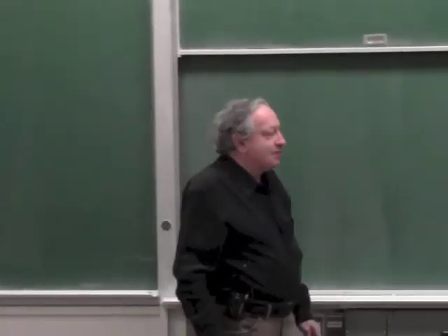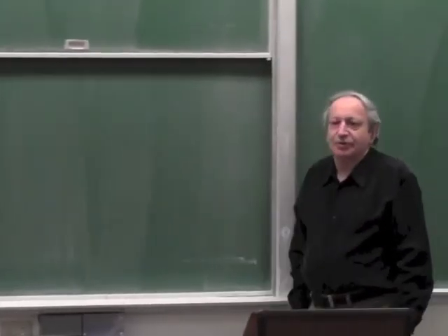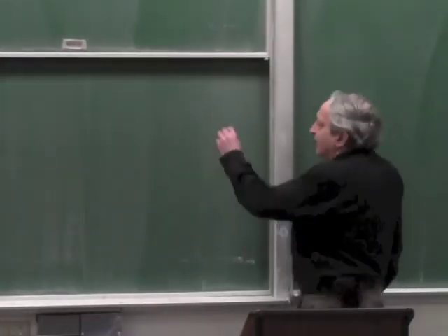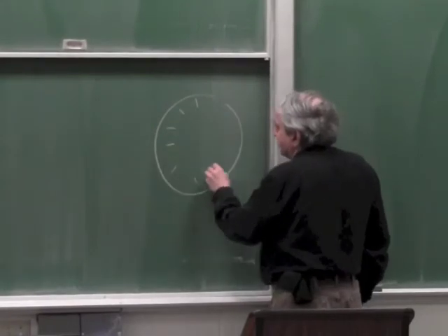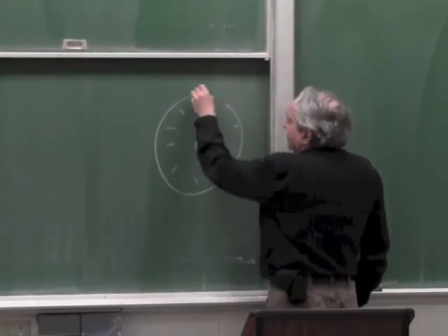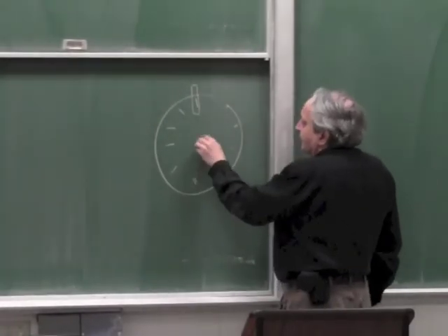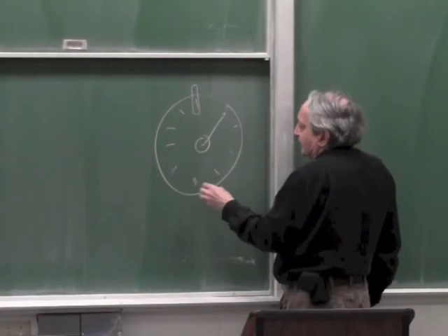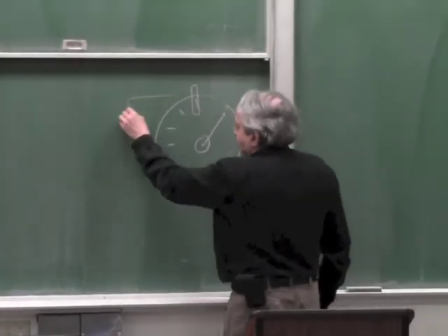One example was how to correct the main error of a rotary encoder, which is a runout, by instead of reading just at one read station, instead of reading just here, and the eccentricity will affect the radius and affect the angular measurement, to read on two opposing stations and average them.